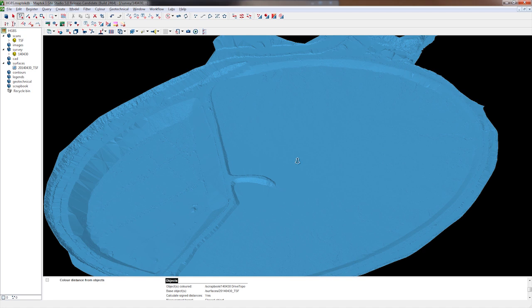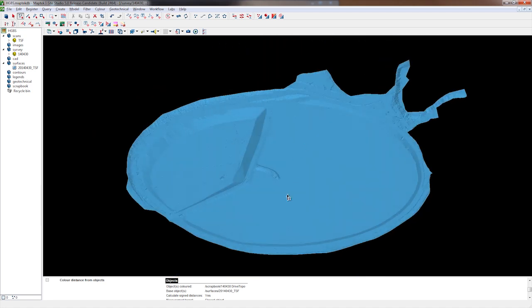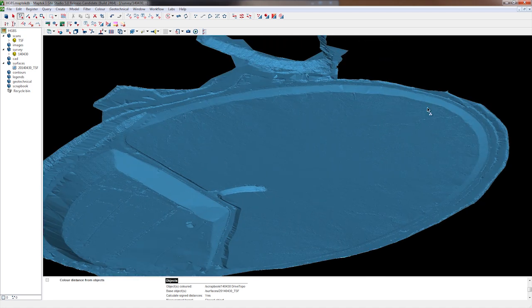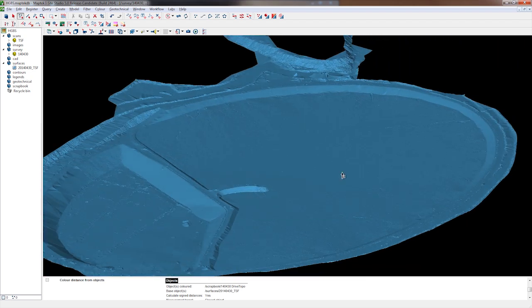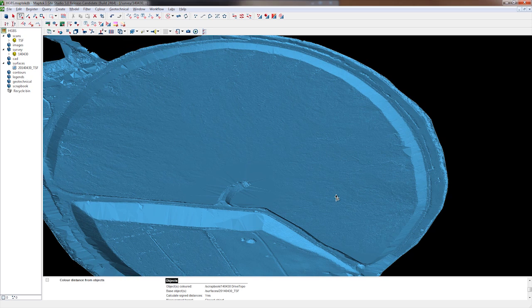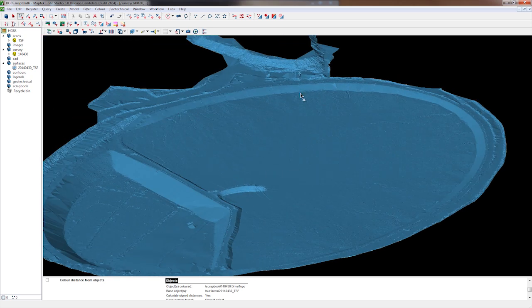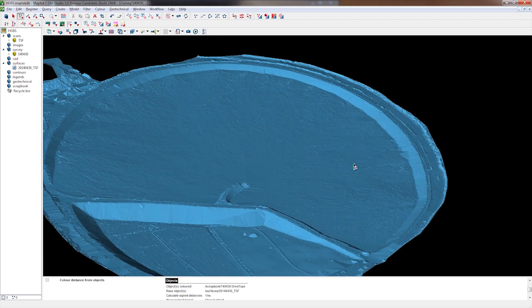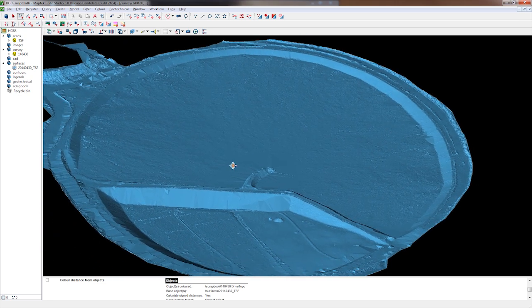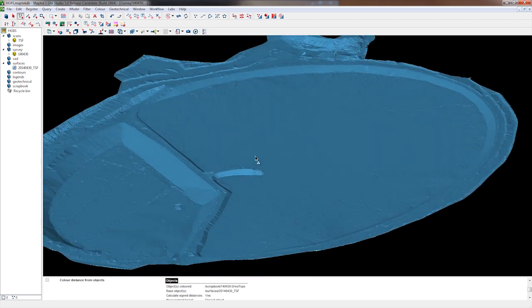Today I'm going to show you how to quickly compare an as-built surface, so this one is of a tailings facility scanned, compared to continuous topo points from a GPS. So I find this great for basically analysing your registered data set and working out where or if you may have errors. Great for reporting for contractors or anything like that as well.